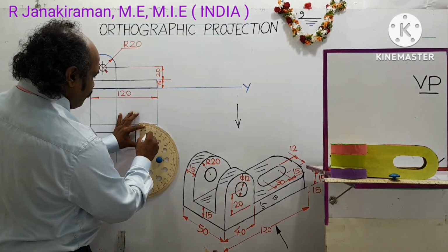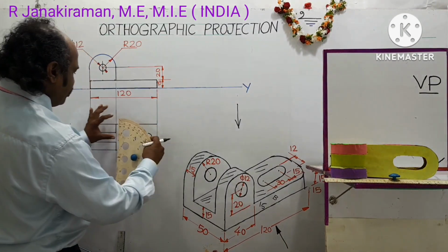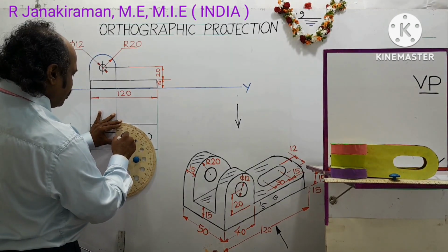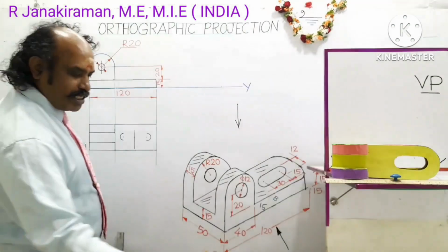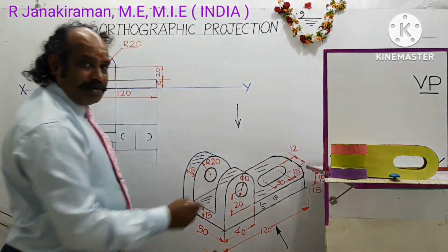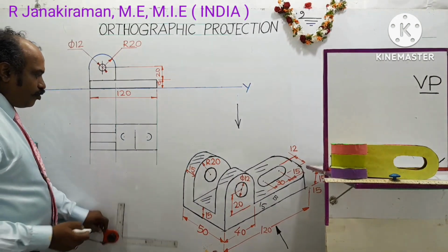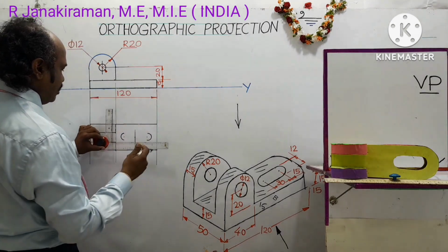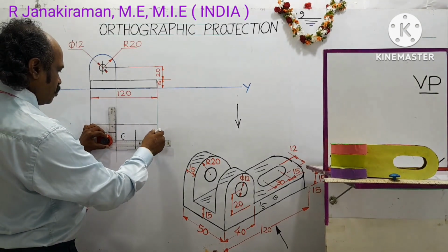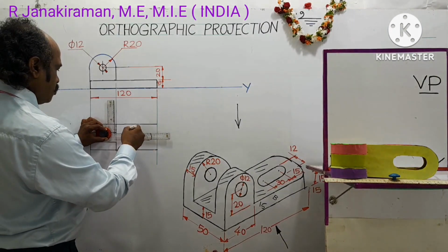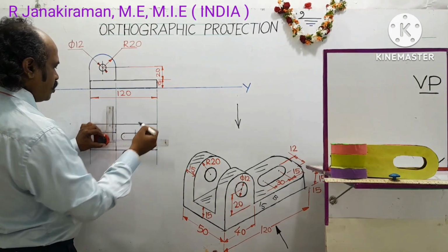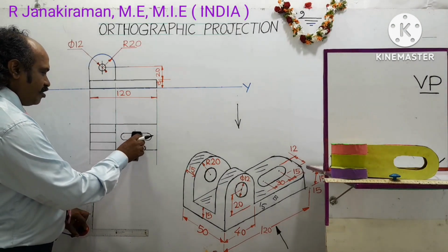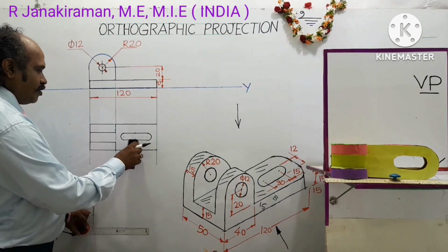With this marked point as reference, draw two arcs, one on the right side, another one on the left side. This shall be done using a compass or pro circle. Okay. For the chosen 6 mm radius. 12 divided by 2 will be 6 mm. Next, connect the two arcs by horizontal parallel lines like this. Okay, right. And if you want, you can erase the lines which were drawn earlier, or you can leave them as they are, no issue.